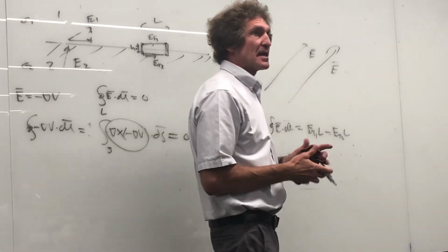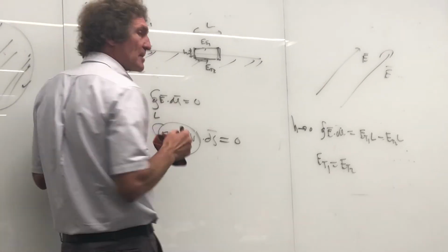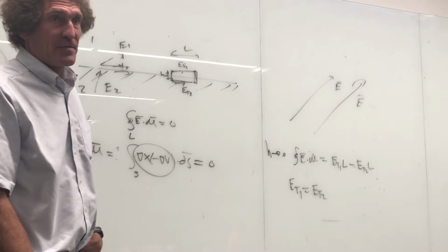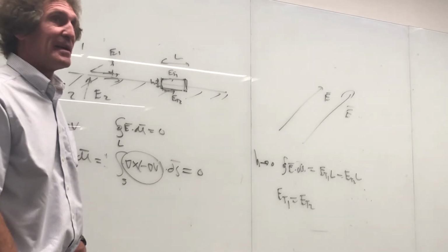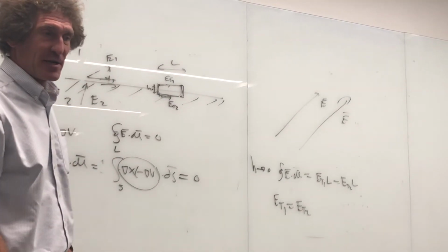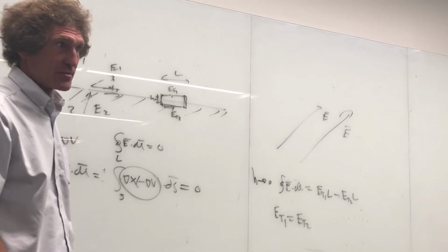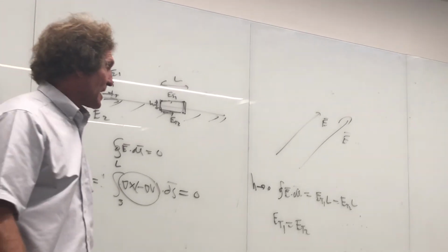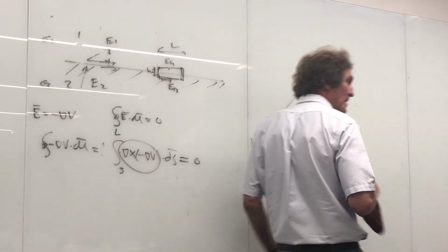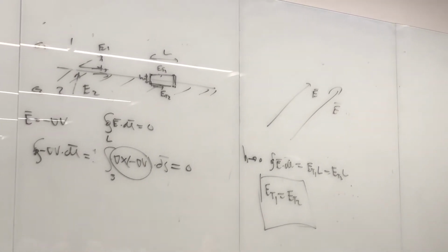It means the tangent electric field on one side of the boundary, just below it, is exactly equal to the tangent electric field right above it, and it has to be. All right? E tan 1 is E tan 2 because there can't be a difference, or when you did a simple closed loop integration, you would get non-zero voltages at the same points of the leads. Would you follow me on this, class? Now that's the tangent electric field. E tan 1 is E tan 2. Remember that always. The next has to do with the normal D field between 2 regions.